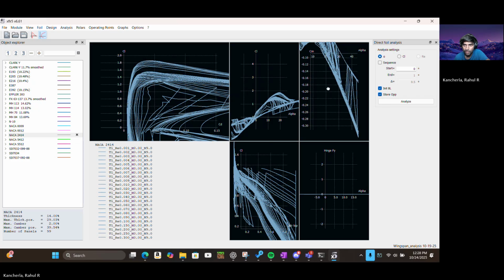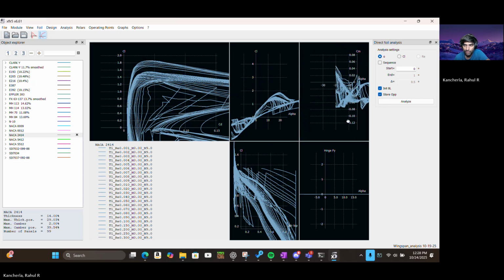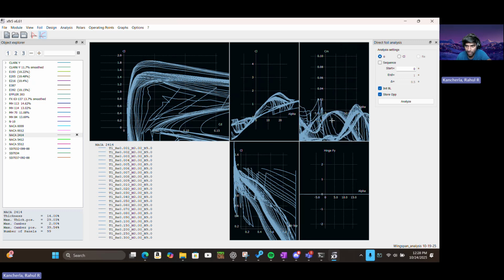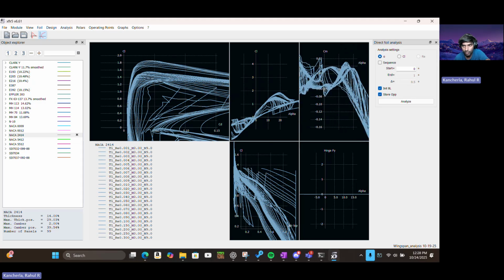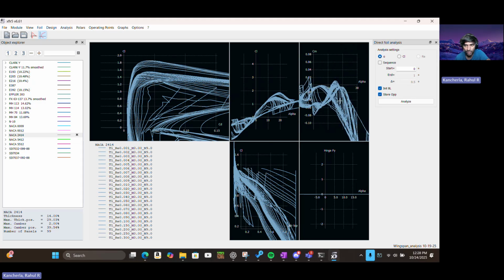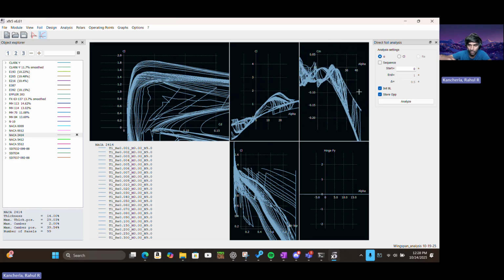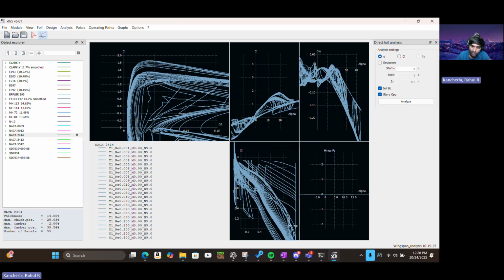And then the pitching moment, that's the stability of, is it going to pitch down, pitch up? It should stay around 0 ideally. This one might not be that stable, at least pitch wise, because it's all over the place, and it's more towards pitch down than pitch up. And then coefficient of lift to exterior top.